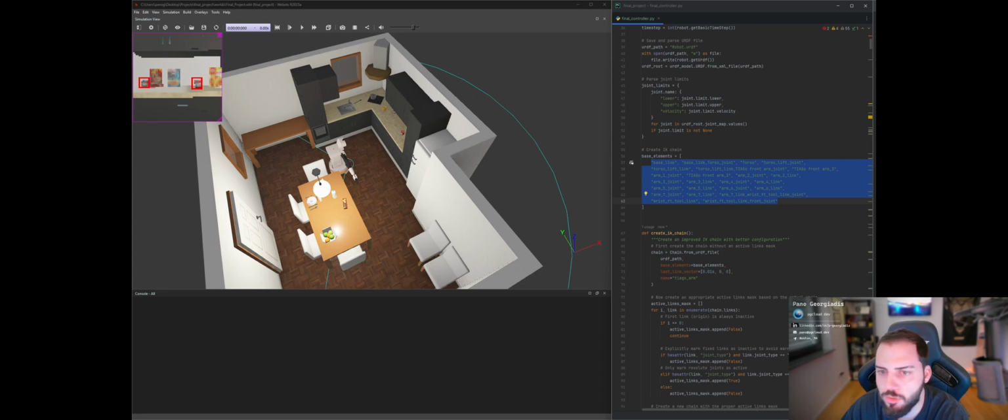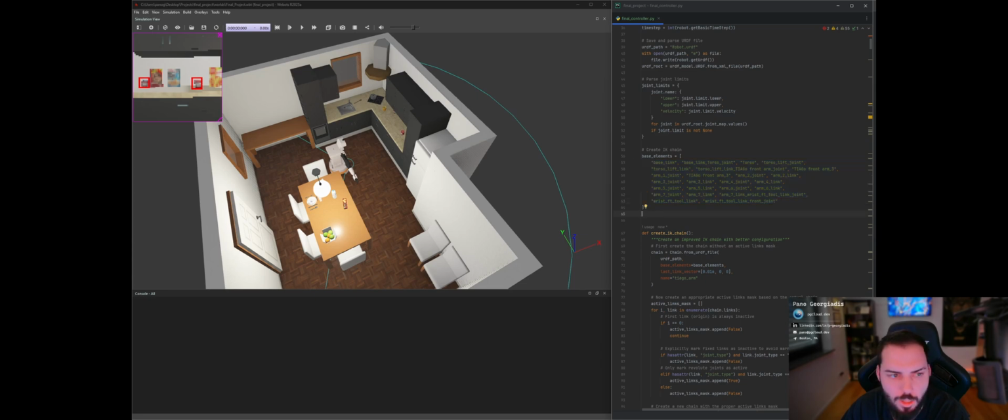What it's going to do is it's going to end up placing its own end effector after the last position, which for this example would be the wrist tool link front joint. And basically what it's doing is, with that end effector in mind, it will calculate where it needs to position all of its arm joints in order to get that end effector exactly where it needs to be in order to grasp, or for whatever use purpose you're using.